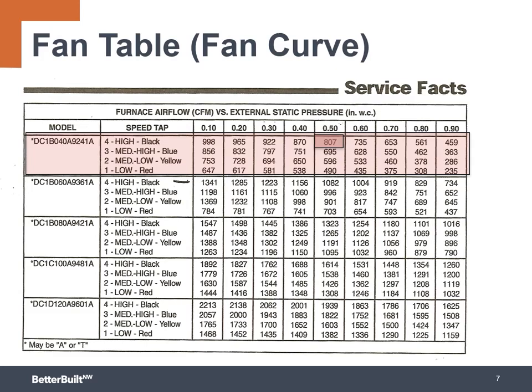As you can see, it lists several models at once. Since we're putting a two-ton system in, we're going to use this gas furnace with a 2-ton, the 24 with a 2-ton blower in it. Notice we have 4 speeds available to us, and underneath the external static pressure that the fan has to operate against, you will see how much air it's capable of moving.